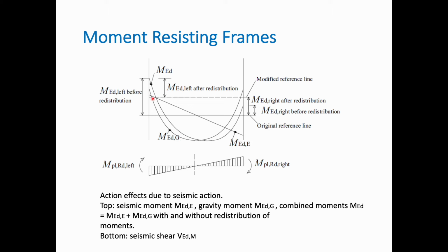We've got the moments due to the gravity forces and the moments due to the seismic forces, and the combined moment of the two, which is the MEd. And we have the before and after redistribution of the moment graph as well. And at the bottom we see the seismic shear forces applied.